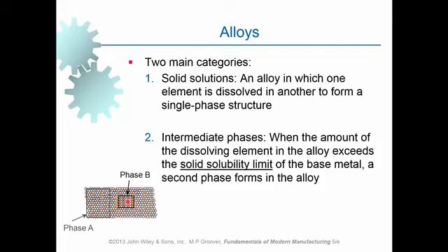Right? The number of slip systems in FCC and BCC are different. And because of that, ductility of the material will change. So we end up with a material with intermediate phase where in some positions it is more ductile, in other regions it is less ductile. So it will affect the overall properties of the material if this happens.